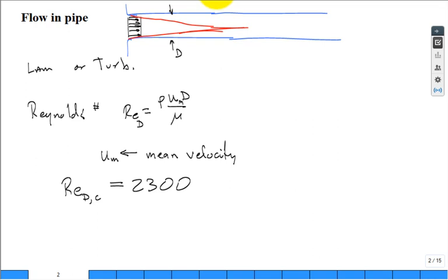And if I sketch the velocity profile down here, if it was laminar, your memory may say that it looks very parabolic. It's a quadratic or parabolic. So this is the center line. And we measure r, the radius, going from 0 at the center line out to capital R, which is the radius of the pipe, the radial coordinate direction. And so here we would have u as a function of r, where at r equal to 0, it's the maximum, and at r equal to capital R, it's 0, some velocity profile.